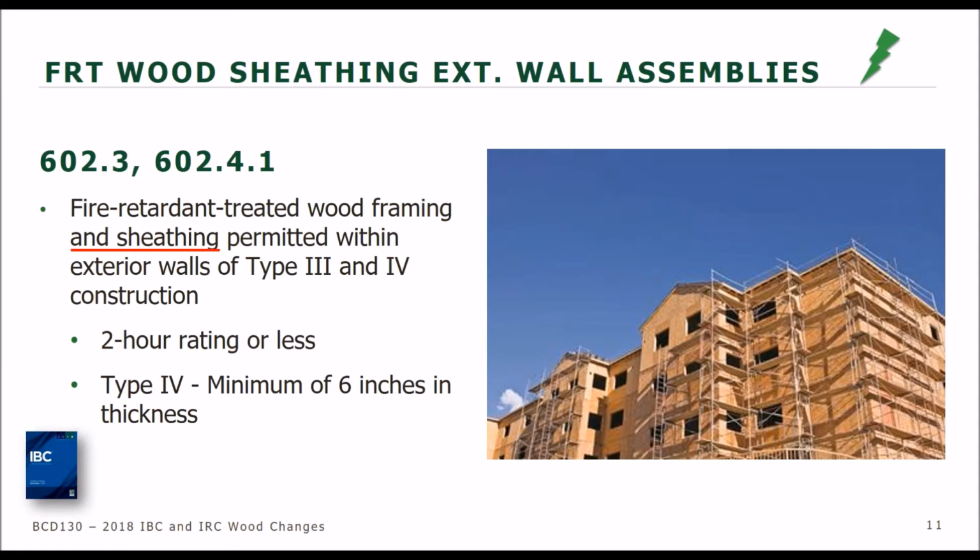Thanks, Michelle. One of the things relative to the sheathing itself is a lot of code officials were misinterpreting the concept of what framing meant. They would say, well, that only means the 2x, wouldn't include any of the other structural elements, which in a lot of cases is the sheathing of the exterior wall. So that's just a clarification of what had been intended all along.